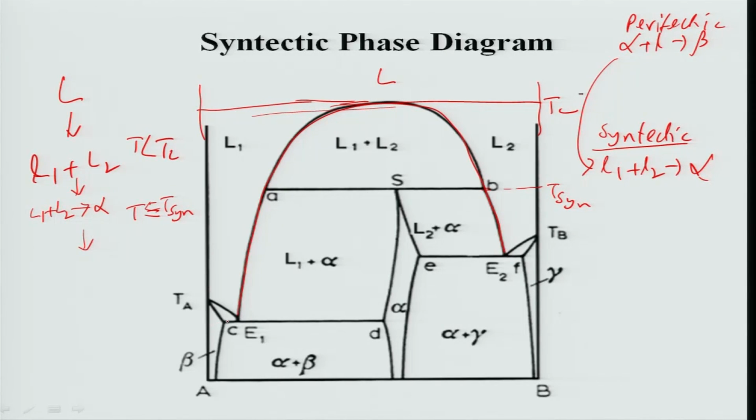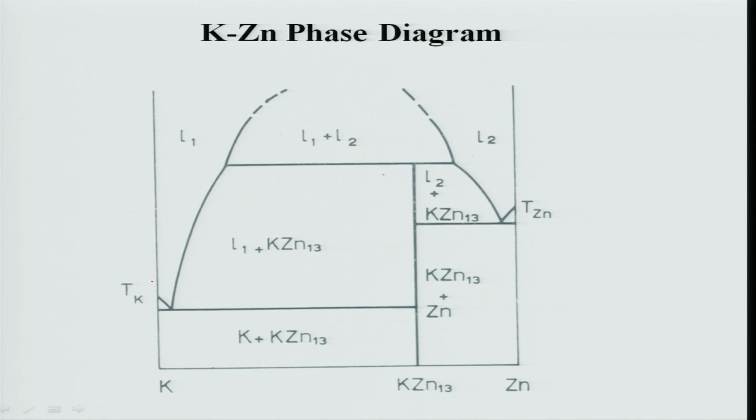There are two eutectic reactions on both sides, one is E1, the other is E2, okay. So depending on composition, either E1 or E2 takes place, nothing else will happen. You can also have peritectic reactions on both ends. I will draw the phase diagrams which will have peritectic reactions now to show you, as that is not very difficult to do. Well, before that, let me clarify that there are very few systems which show this kind of phase diagram.